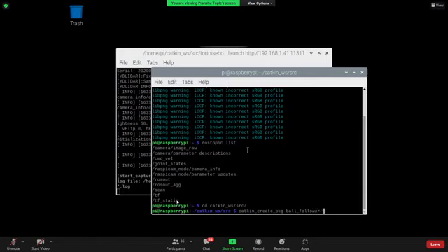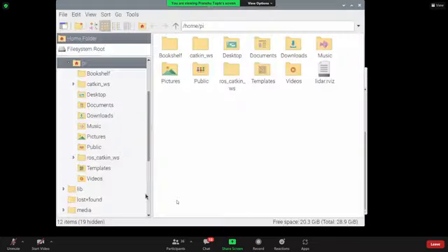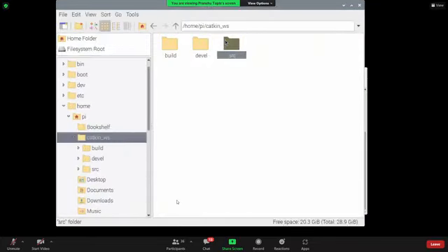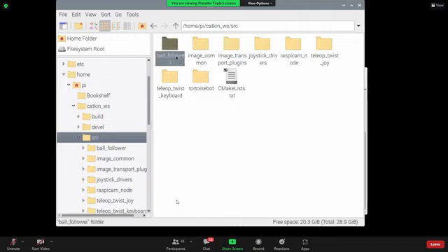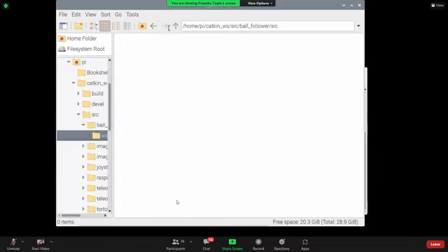and I will be giving the dependencies. So what is my dependency? My dependency is rospy. So it should be dependent on rospy. If there is no rospy, it won't work. So rospy is the Python library for ROS. I will press enter and it will say successfully created files. So now if I go into my src, catkin workspace src, you should see there is a folder called ball follower, and it will have this src folder in which I will make my Python file. Okay, so now let's do that.